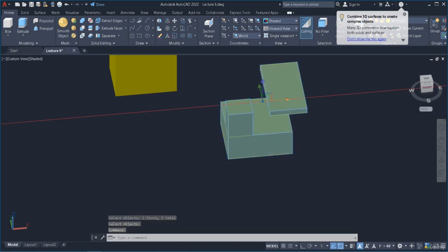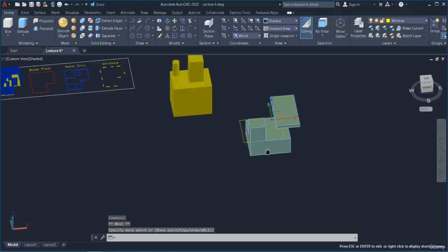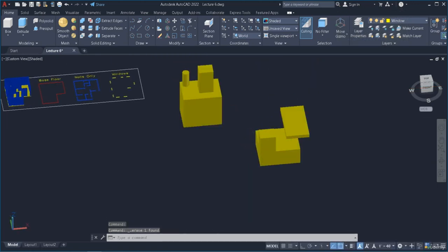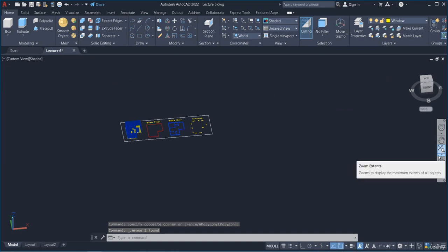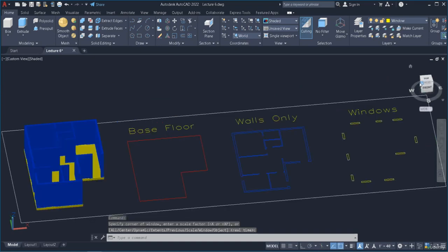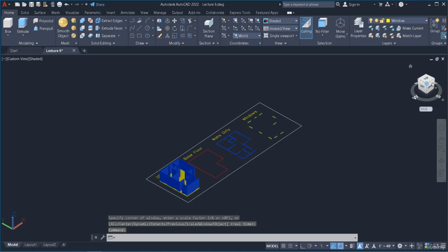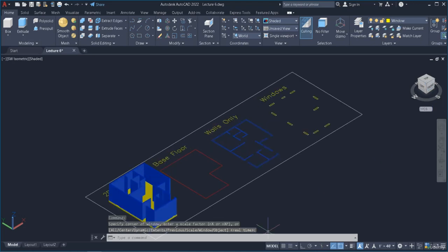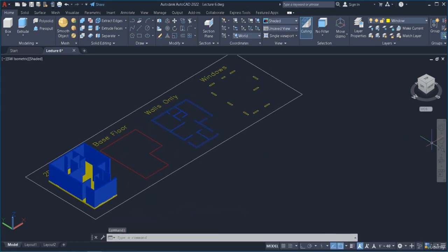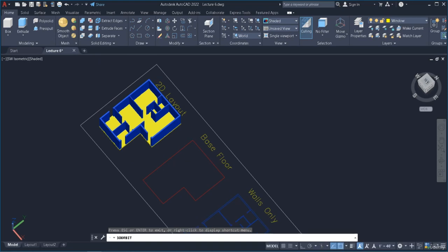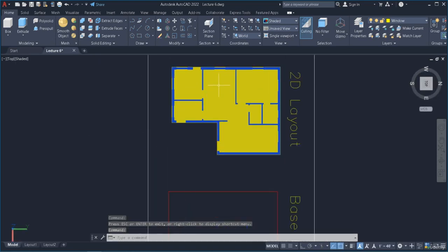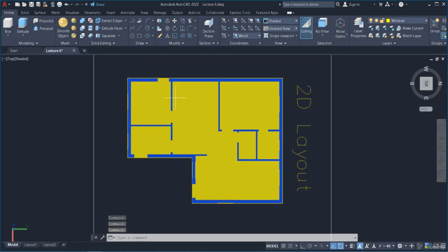After doing union, now if I select one object and move, all of them will move together, like this one. So in this way, we can actually merge 2 to 3 bodies to act as one body or one object. We will use this concept when we create the spaces for the doors, so that our walls and the spaces above the door would be considered as one object.